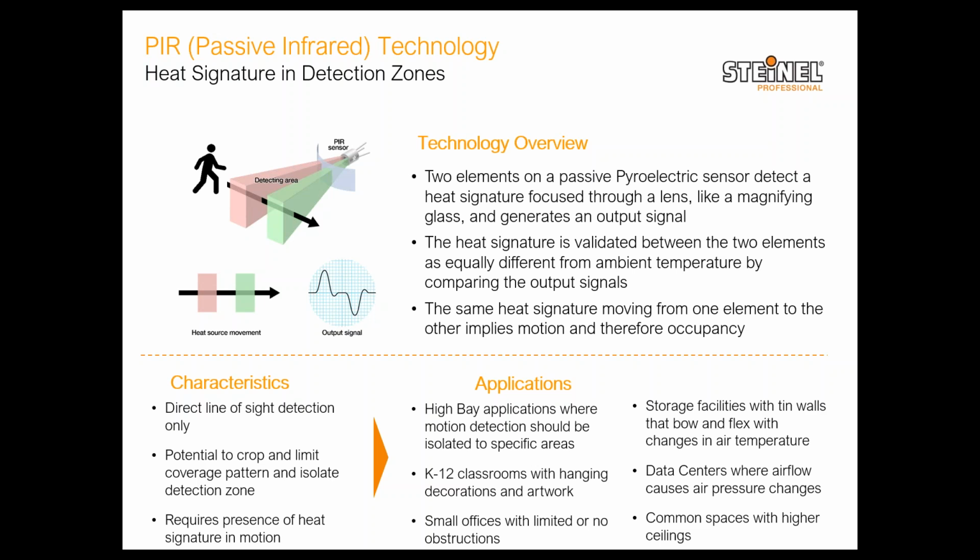So if you have, let's say, our IR Quattro HD sensor with 4800 switching zones, you would more than satisfy the small movement requirement of NEMA very easily. And the definition of that small movement as per NEMA is a human arm moving 90 degrees, which is quite a big movement. If you think about it, it's not really minor. Your arm is moving completely from one direction to another direction.